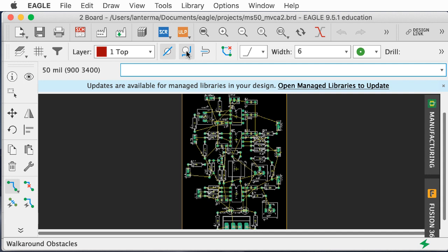If you made a mistake in the layout and your traces are kind of spaced out a bit, you're more likely to be able to cut a trace if you need to without damaging another trace. Also, if you spread things out a bit, you can use various mill machines, or you can use some sort of photochemical process and probably have better luck than you would if everything's kind of jammed up.